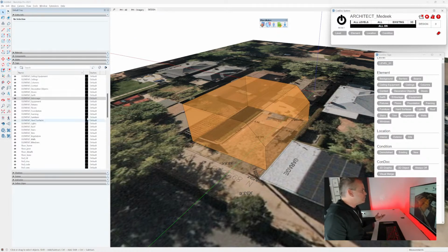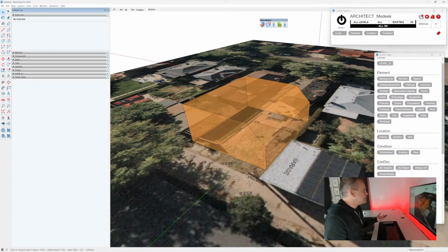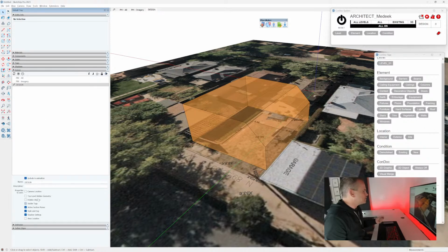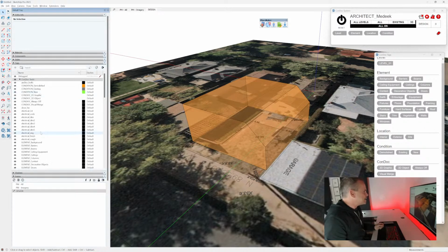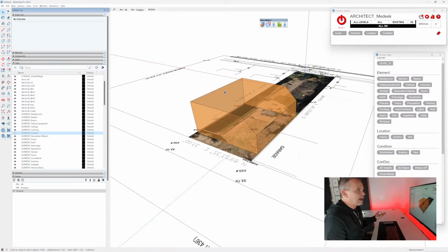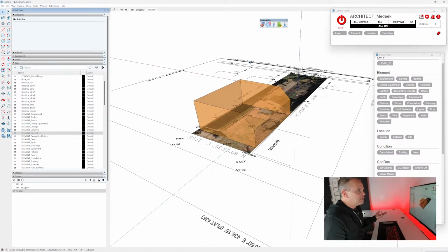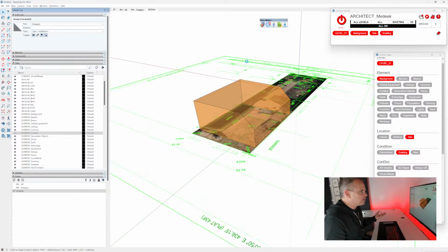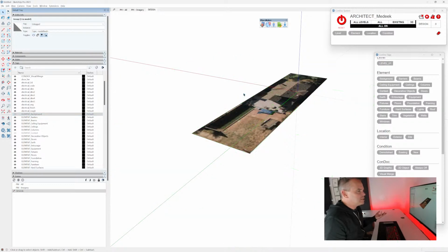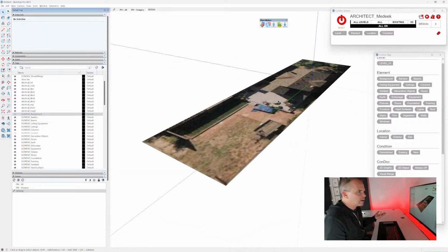Typically what I would do is go to my scene and turn on my visible tags, and then go to my tags and maybe turn off context. I really don't need to see all that as I'm working, right? And as far as this background goes, I don't need to see that at all times either. So this is what I want my design scene to look like.